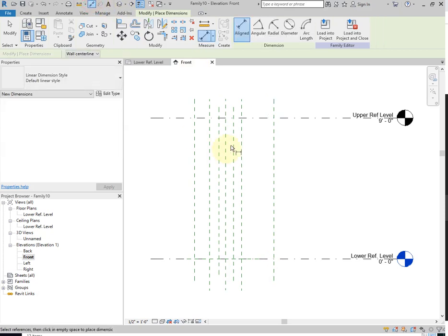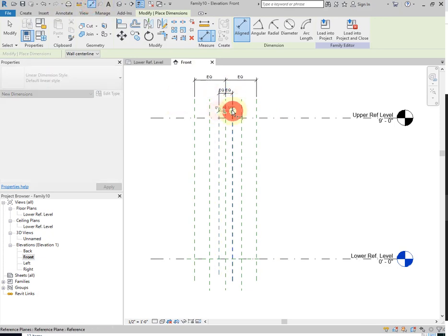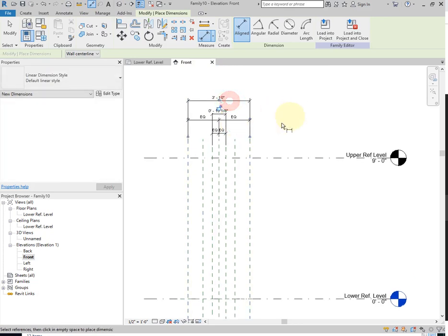So this is important where you start really tracking what you're drawing. So we want to make the small one equal about the center, the large one equal about the center, and we'll add a dimension for the small diameter and a dimension for the large diameter.